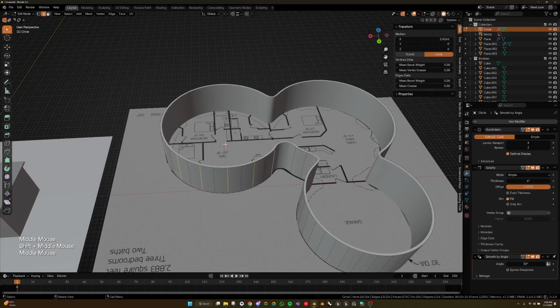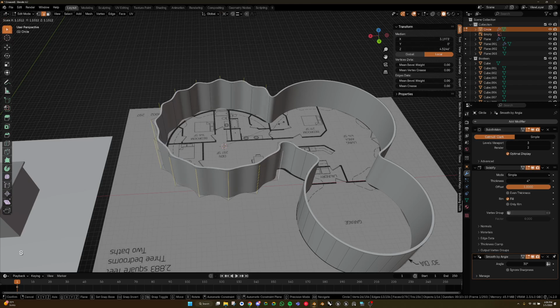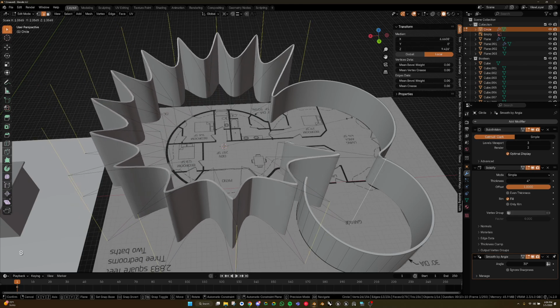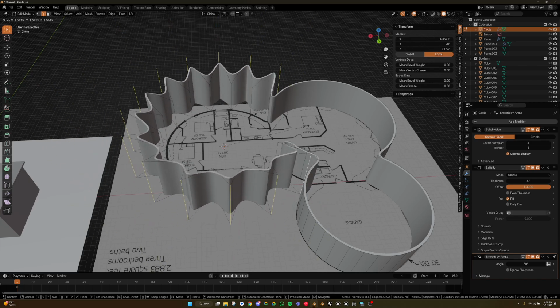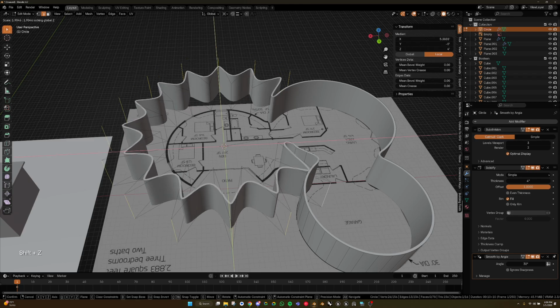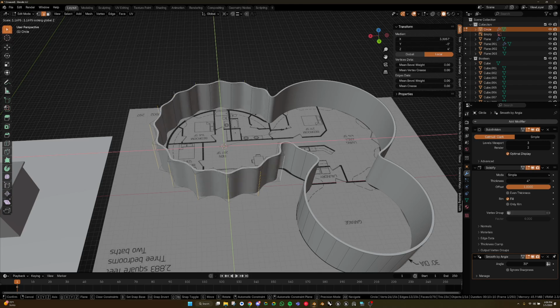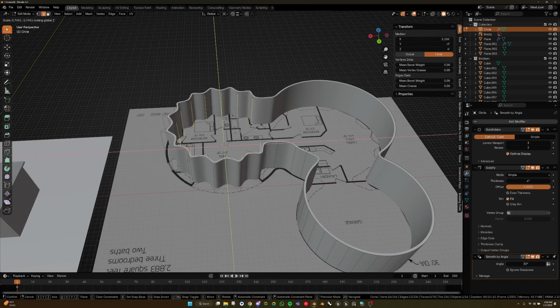And if I want to scale along the center and scale them outward, what you can do is have your 3D cursor as the reference point, scale, and then so they're going to get big, so you want to just keep them on the same axis. So Shift Z, and that just does that. So you can do something really cool like this, right? You know what I'm saying?